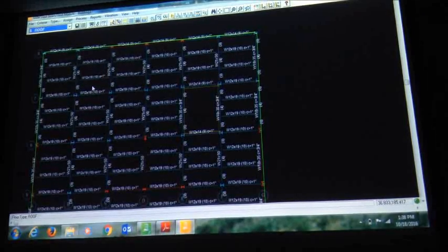What is C? C means camber, okay? Say for example this beam is a 12 by 19 beam, 1 inch camber required, and within brackets 10 means there are 10 studs required. Studs are those bolts which actually keep the concrete and the beam together. Once we are in the last week, I'll tell you a lot about the studs.